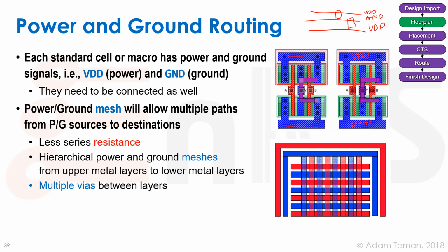However, we can have that large resistance, as we saw before, going through these long wires. So what we want to do is make the resistance from wherever the power pad is until it reaches each and every gate much smaller. And that we usually do with what we call a power mesh. Okay, so what we'll often do is take the power pads that provide VDD from the package. They'll be connected to rings, VDD and, let's say, ground. From the package, they'll connect to a ring that distributes it well. There probably will be several of these VDD ground pairs from outside, so we would say we have sort of an equipotential around the chip.